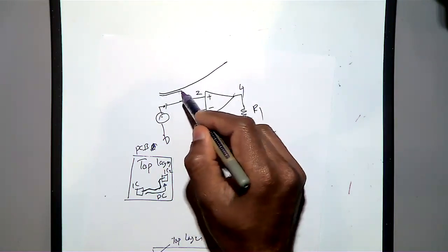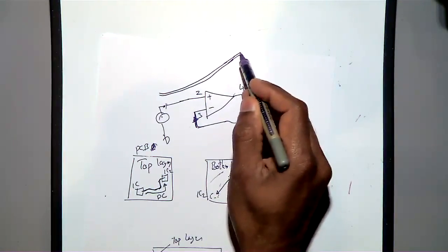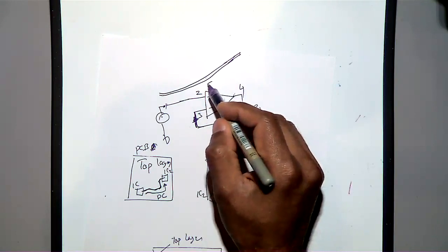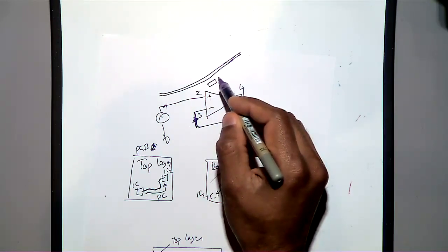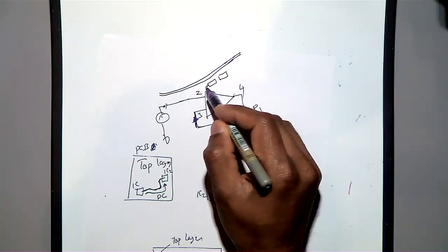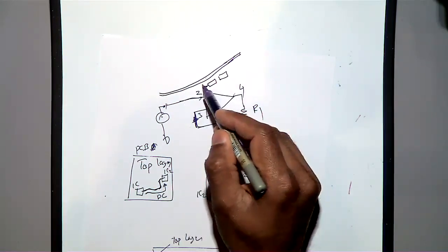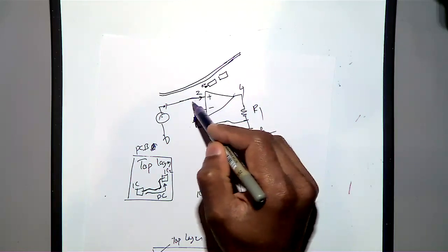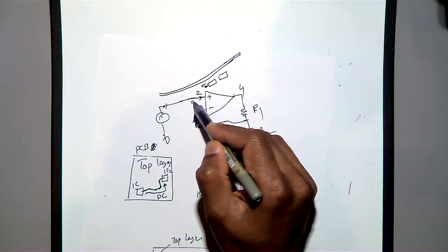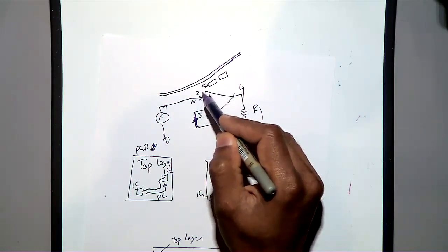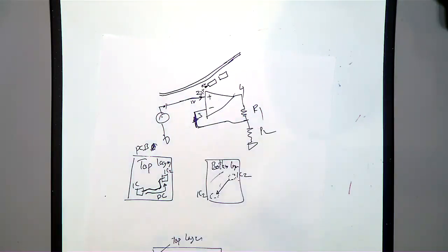That is one example, another PCB track, or you may have another capacitor footprint here, and then this is the ground. When your signal is going through this one, this is at 0 volt, or here the signal level is, just exaggerated, 1 volt. Then there is a separation here, so this can form a capacitor. You know what I meant?